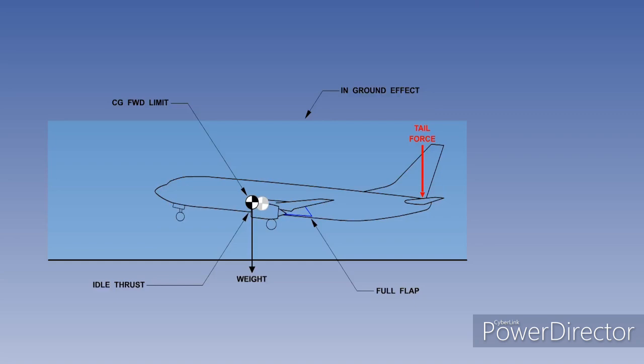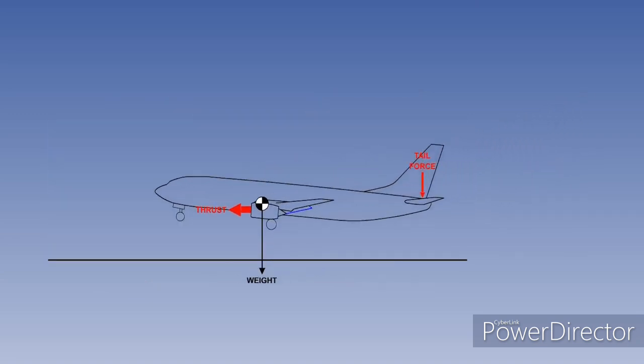Each of the longitudinal control power requirements are critical for high longitudinal static stability. If the forward CG limit were accidentally exceeded, the aeroplane may encounter insufficient controllability in any of these conditions. To conclude our study of longitudinal static stability, it must be remembered that the forward CG limit is set by the minimum permissible controllability, and the aft CG limit is set by the minimum permissible stability. You must keep your aircraft CG within the forward and aft limits at all times during the flight.